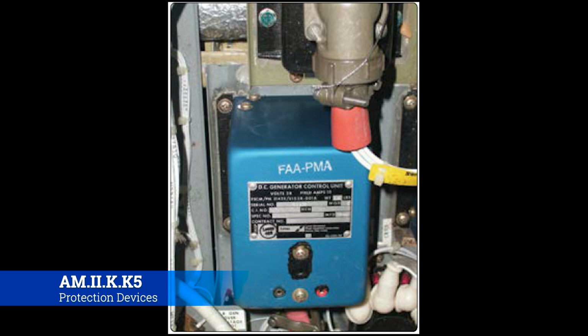Okay, so this is a solid state device, often called a generator control unit or a GCU. Now, I'm going to use GCUs probably for the rest of the time because this is the most common way to refer to them. But effectively, they're kind of like little computers that essentially say, like, hey, look, is the voltage correct, and what do we need to adjust to get that voltage to be correct?